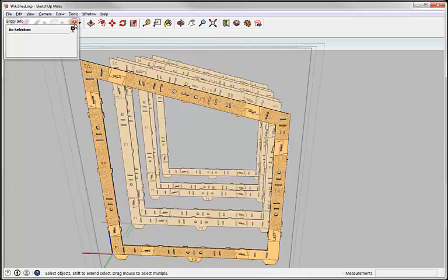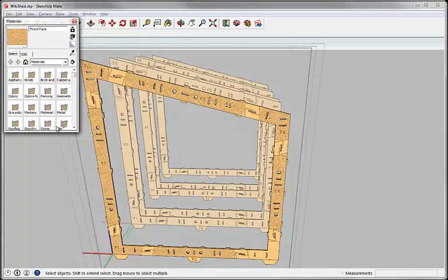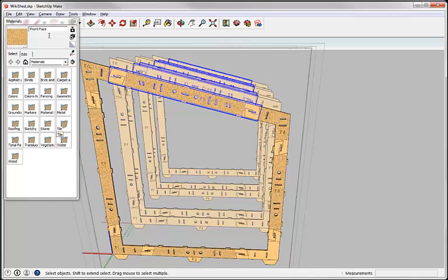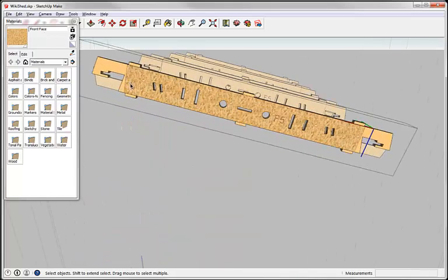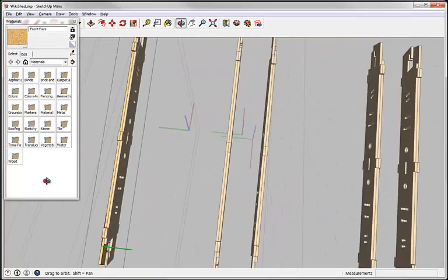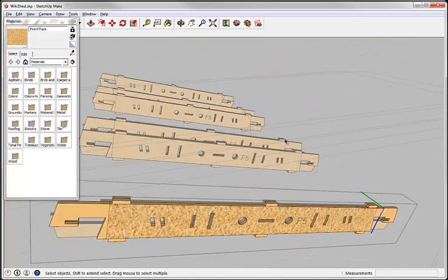We do that by allowing you to specify a particular material. So if we look at window materials, what we have inside this is this front face material. Any place that's been painted with the front face material, we would know when we import it that that's the one we want to have at the front. And if we look back, on these spars, only the one face has that material.